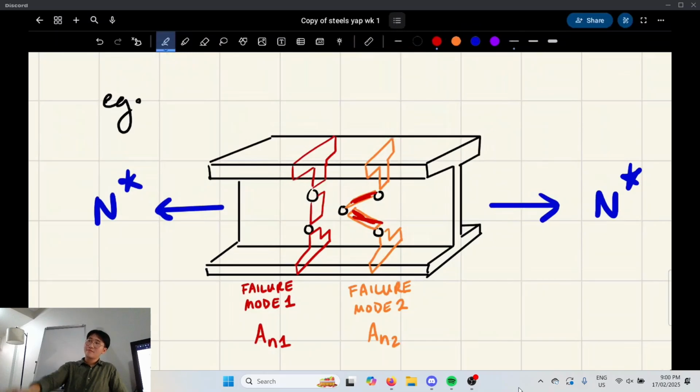It's reduced on this axis. But then we're stretching it on this axis. Does that really? It will still count. It still counts as an increase in cross-section area. However, which one's got a net bigger cross-section area? Sorry, between failure mode 1 and 2. Failure mode 2, in this drawing maybe. But in reality, in general, one. But you have to check for both. Because the holes will reduce the cross-section area, but the diagonalness will increase it. So it depends on the ratios.